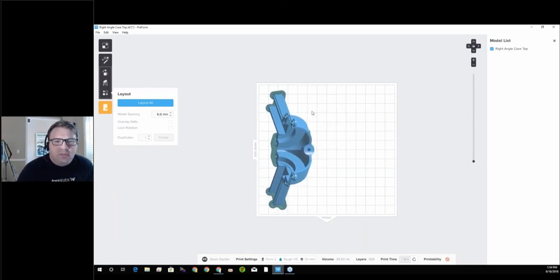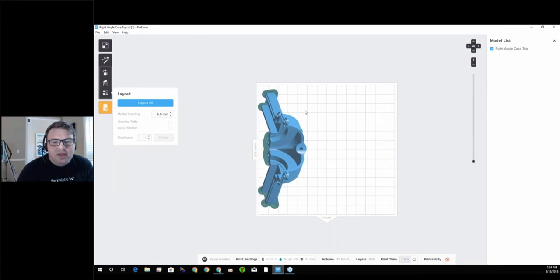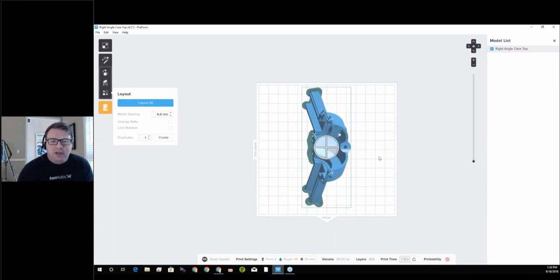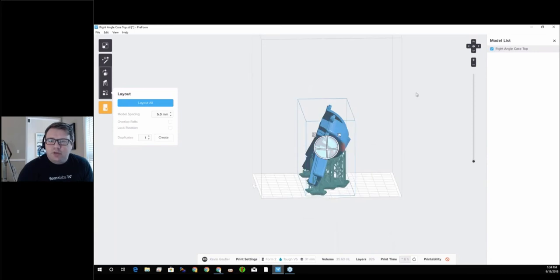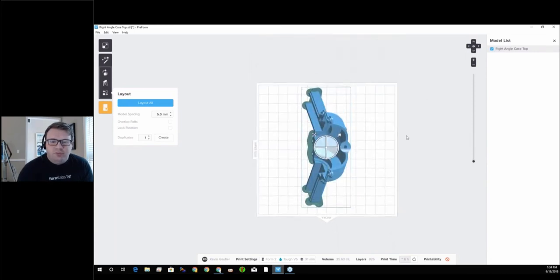If you were to bias the part towards the wiper side, it would print slightly faster because the wiper only has to go as far as the part. It wouldn't have to traverse the entire build platform. So that's one piece of advice. But I will say that it's fairly important to think about which direction the Form 2 peels in.